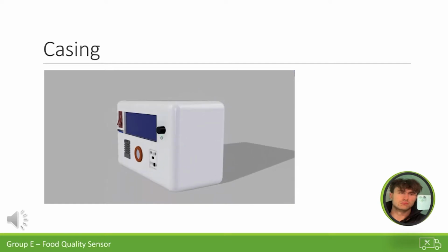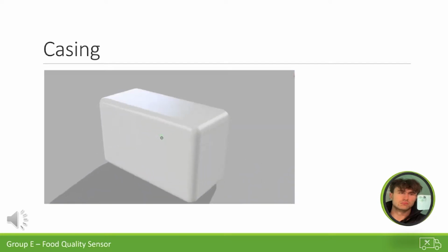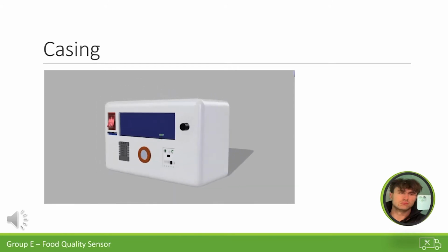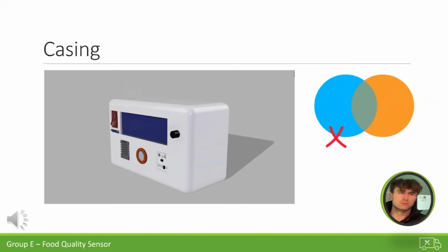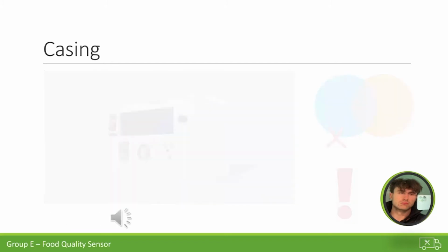Once all the component models were present, it was then onto the matter of inserting all the components within the box to test for fit. To make sure there was no component overlap, specific non-overlap rules were used on a per component basis. This meant if there was insufficient space for a component to be placed, Fusion would raise an exception, allowing action to be taken accordingly.